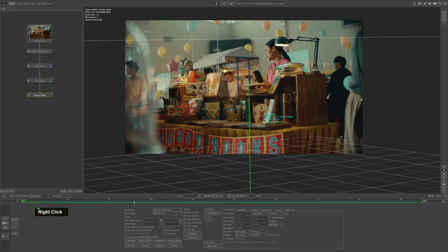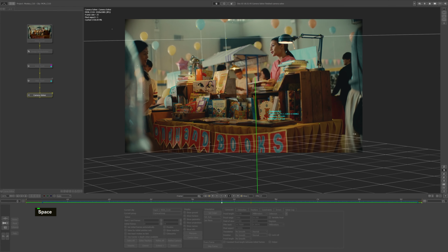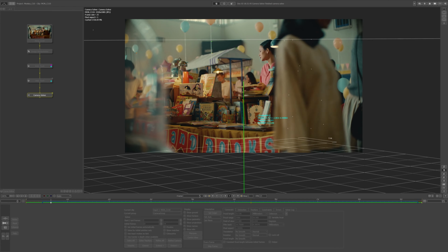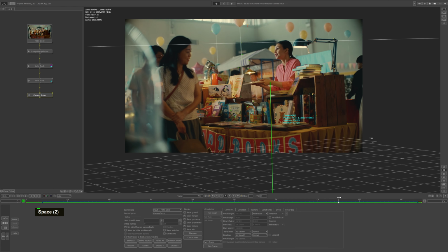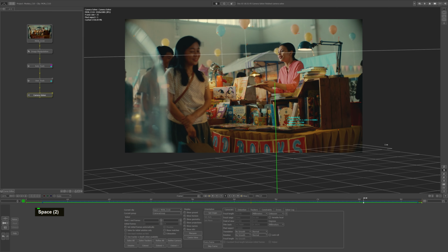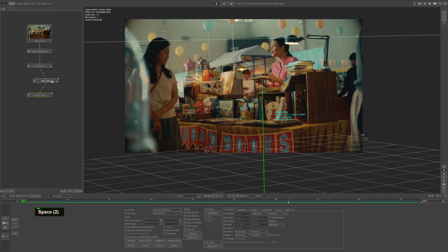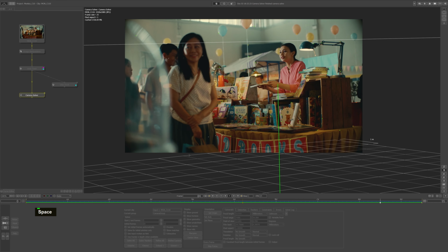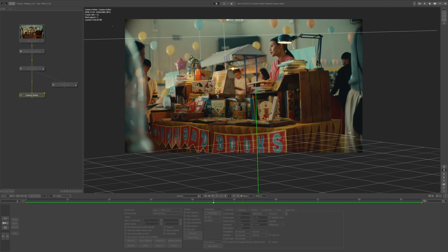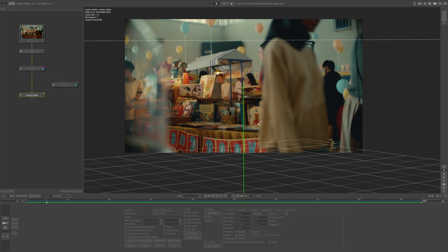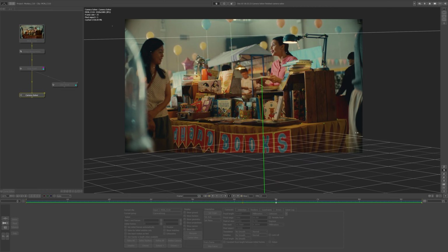So you can see they have some sliding. Sometimes you have to check what is causing the problem. So here I think it might be the cause of the user track. I don't want to use a user track for here. I can just unplug and plug directly here, and then I'll solve again. Yeah, I think the user track in this duration is causing the problem. So the auto track is good enough.